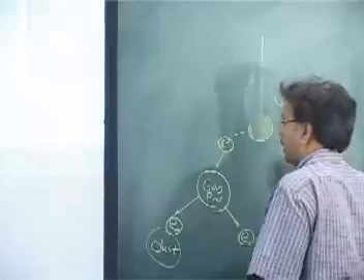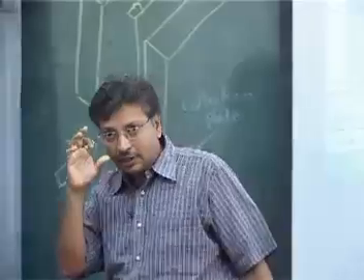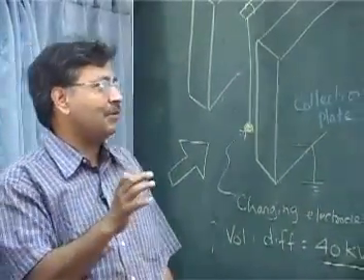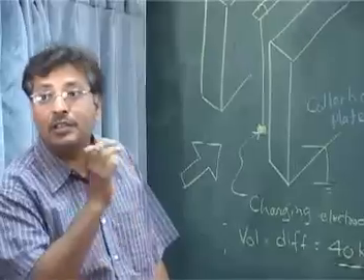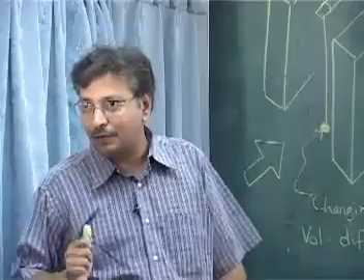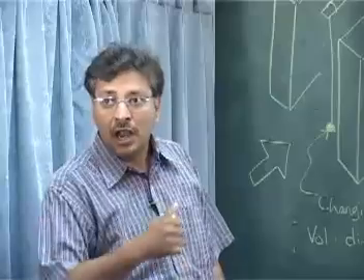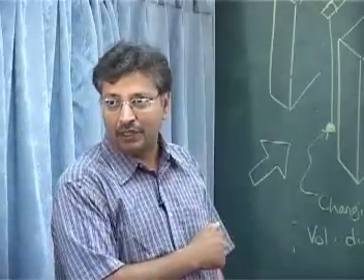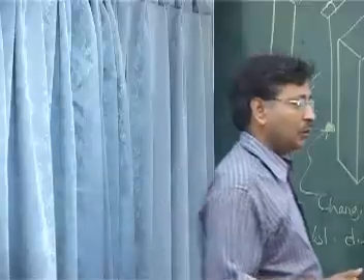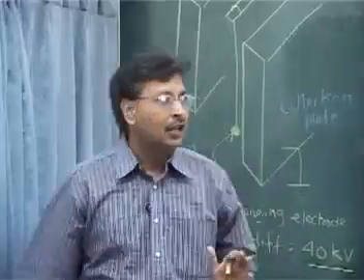And in some of the ESPs, at least some of the experimental ones, you can see through the glass the corona being generated, and that corona is key. If the corona is not being generated, it means your ESP will not work, because you are not producing enough electrons to sit onto the particles and drive them towards the plate. So this is the mechanism, or the physics if you like. Then there is mathematics for this that we will not see so much in detail, but I want you to get the sense of it.